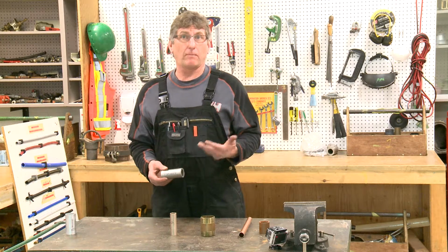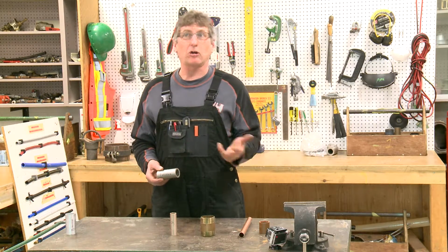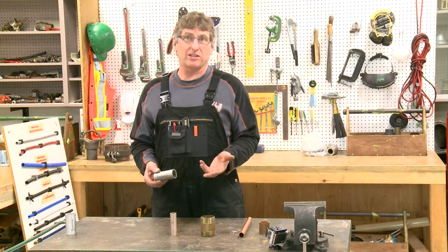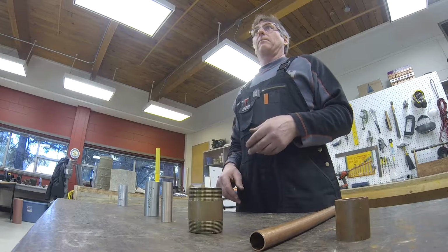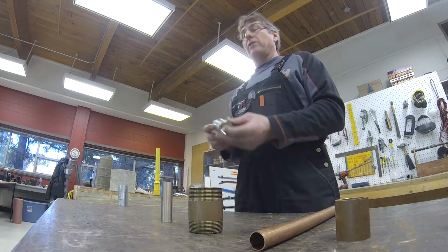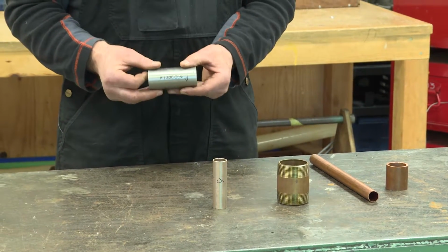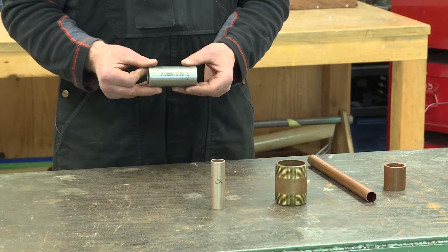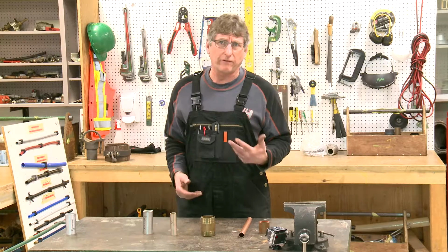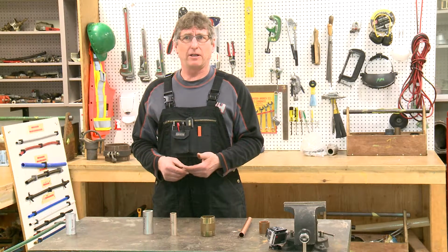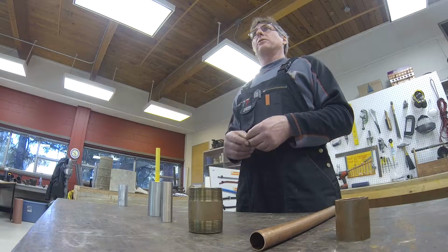Another alloy is called Monel, and we call that a nickel-copper alloy because it has at least 63% nickel and small amounts of other metals. I don't have a piece, but it looks very similar to 70-30 copper-nickel. It has the added characteristics of maintaining its toughness over a very wide range of temperatures. This gives it additional uses in refineries.